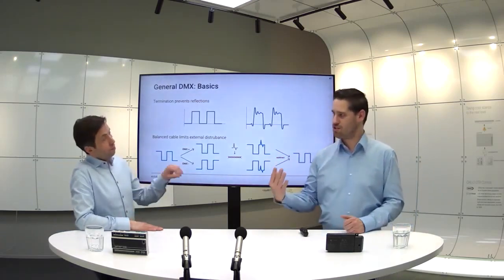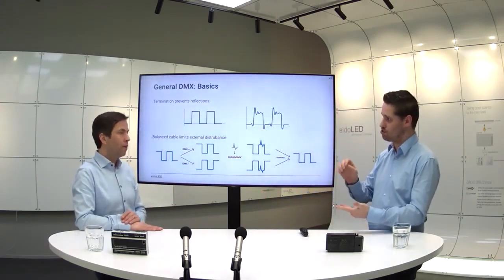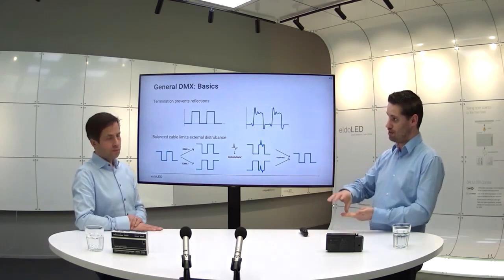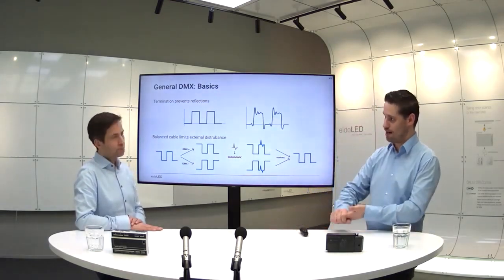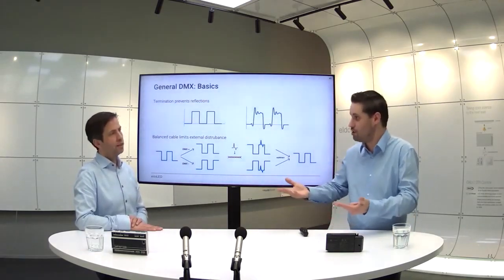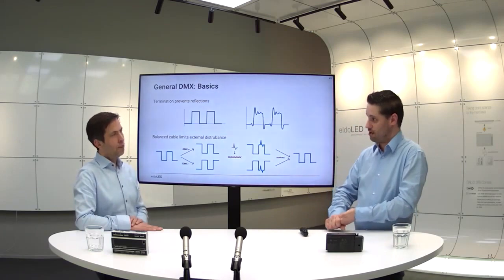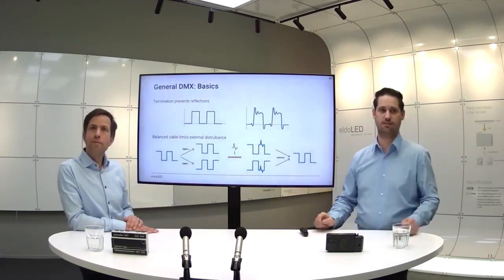And it is not only 2 conductors, positive and negative, but you need to shield. Exactly. So I would say DMX is never 2 wire. Correct. DMX is 2 wires, including a shield or a ground reference, or 3 wires. Correct. But at least a twisted pair. Shielded twisted pair is indeed the cable you need for DMX.